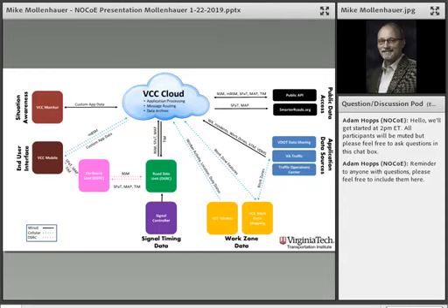And up in that Northern Virginia region, VDOT operates the ATS D4 firmware on the intersections that we're engaged with. They have about 1,400 that are deployed in that entire environment. We're tapping into about 30 of them. And so we had to work with ATS, or Advanced Traffic Solutions, to develop a custom interface to push that data from the controller to the RSU so that we could compute and create and format and broadcast the SPaT messages coming out of that unit.